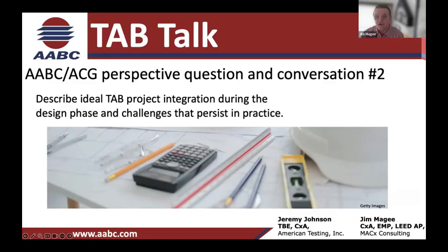It doesn't mean your ability to balance. It means the design ability, the design installation, the design, I'm going to call them components, right? Dampers, valves, at locations. Every once in a while you're going to get this kind of hybrid approach, and you've got half pressure dependent, half pressure independent, right? And then you have, say, a damper, but there's no way to lock it down or set it right. Well, dampers are not all created equal.